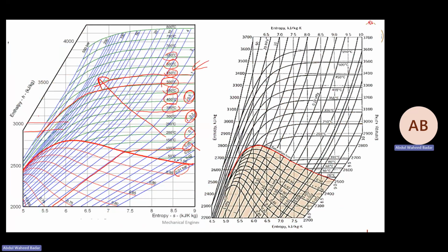So these are temperature lines, and here the temperature values are written. And what are these horizontal lines? Enthalpy. And what are these lines? Entropy. So you can directly read entropy or enthalpy from this chart. Just locate the point and read it. Yeah. If the pressure is between these two, just imagine where it is, for this course, for the exam only.